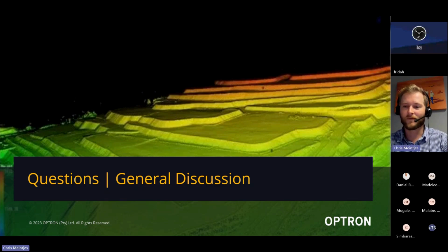Dave, yeah, TBC and RealWorks, very similar scan registration. It works basically the same. Now you can do the cloud to cloud stuff. I've used both to test. I've done two scans of two separate areas with about a 20% overlap in the middle, and I've tested in RealWorks and Business Center, and I get very, very similar results.